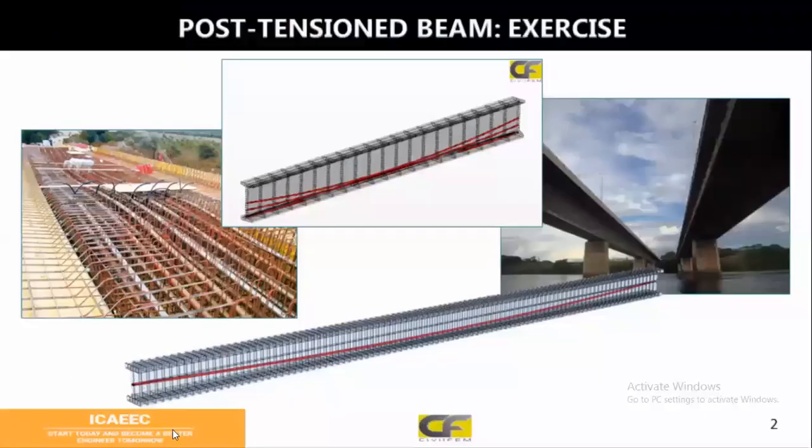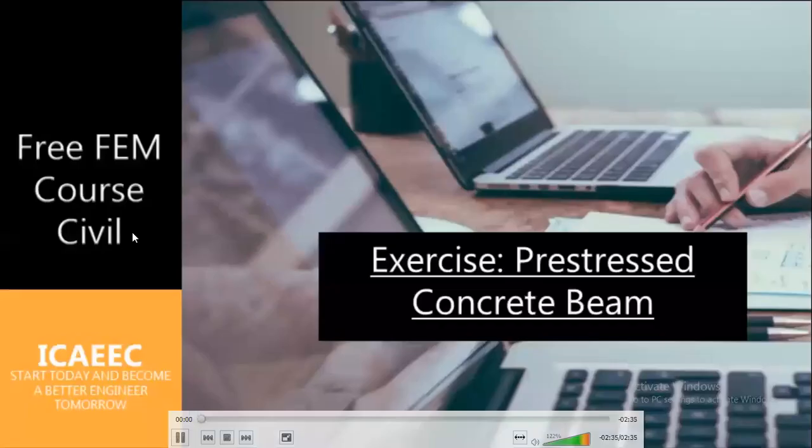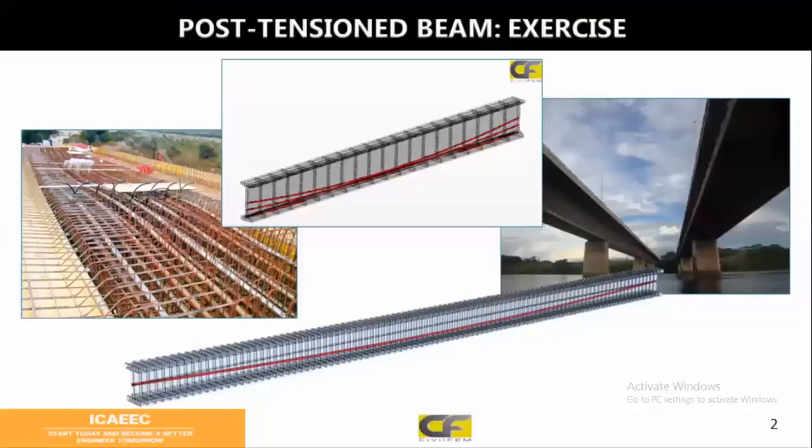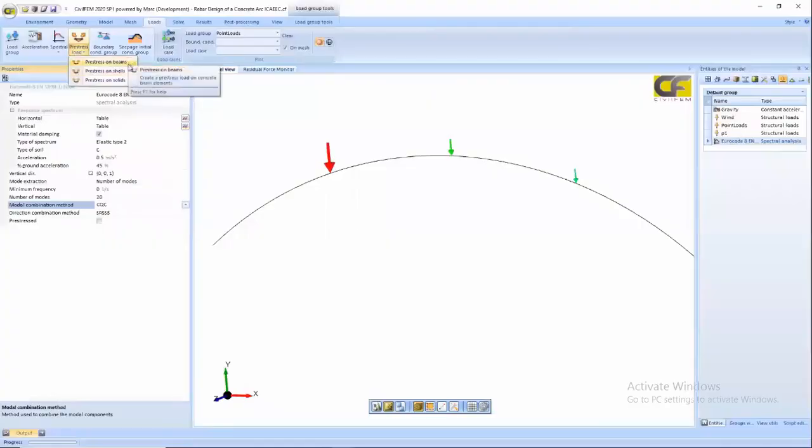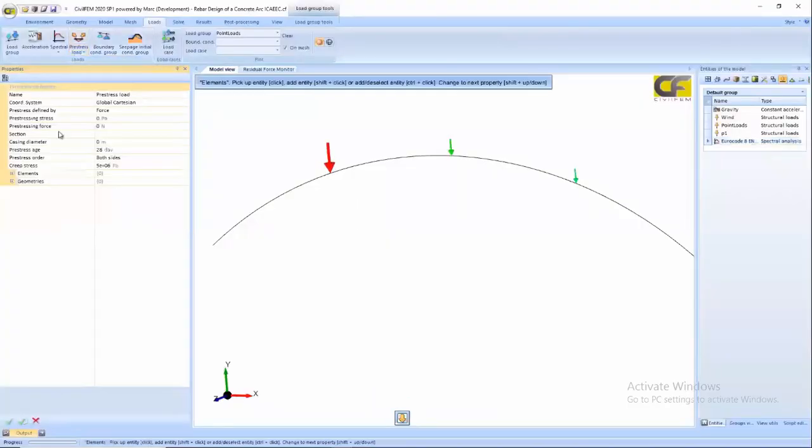You can pre-stress beams and shells. To do that, you just need a section. Have not defined the section of a tendon, how to define a cable section, casing, how to pre-stress it. There will be an example of a pre-stressing tendon soon as well, and just select which entities to pre-stress. There are no new elements to be defined for the pre-stressing tendon, but the equivalent forces will be applied to the model.